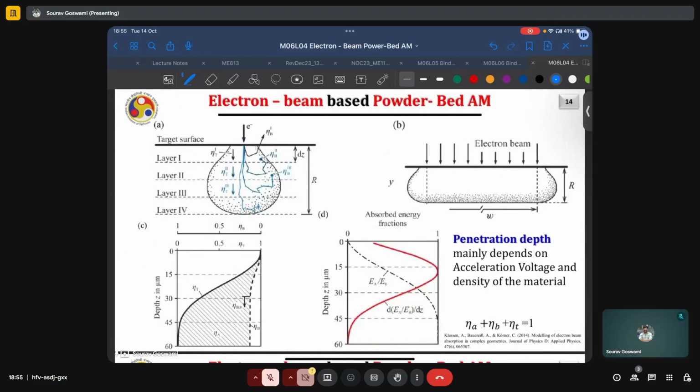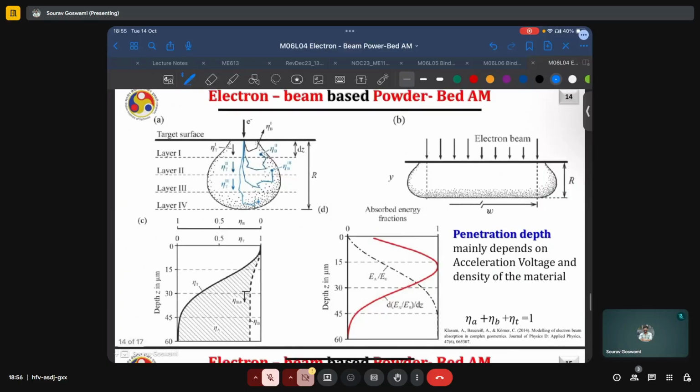The present slide also summarizes the typical melt pool shape which forms under the action of an electron beam. And we can see that it is slightly different from the melt pool which typically accompanies a laser beam, and that is because of these small bulging regions to the sides. We see that in between there is almost a uniform region of constant thickness, but towards the ends there is this bulge, and the reason for that bulge is the nature of the electron and material interaction.